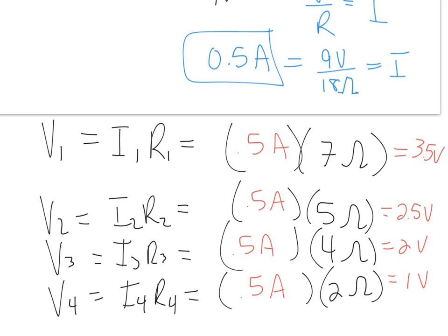So your multimeter is good to use around the house. If you need to figure out if there's a shorted circuit somewhere, and you want to know if there's voltage supplied to something, why it's not working, believe it or not, these are the things you would stick into an outlet. You can literally go to an outlet, stick one in one end, one into the other. I still wouldn't do it. So this is a setting for up to 200 volts. This is only 120 volts.